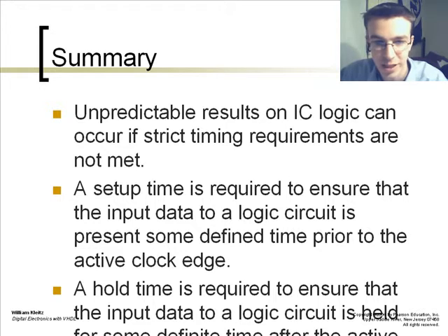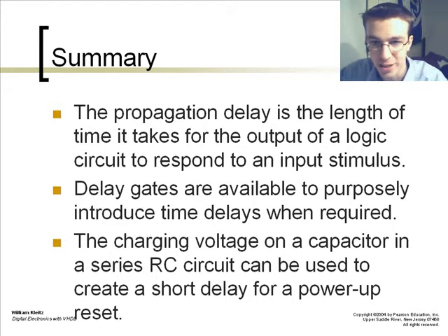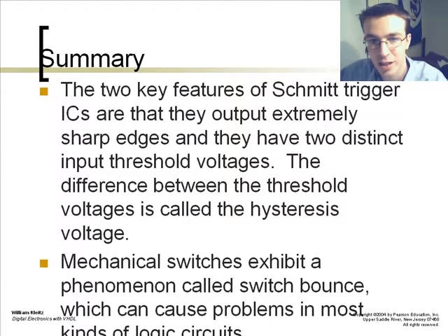So in summary of this chapter, you can say that the flip-flops have various levels of time propagation. We have setup time, we have hold time, we have propagation delays, the length of time it takes for the output of a logic circuit to respond to an input stimulus. Delay gates are available to purposely introduce time delays when required. The charging voltage on a capacitor in a series RC circuit can be used to create a short delay for a power-up reset.